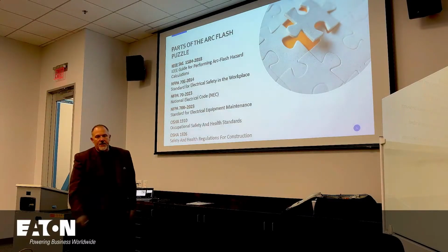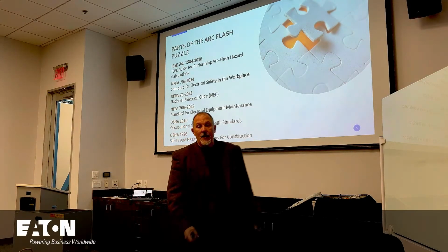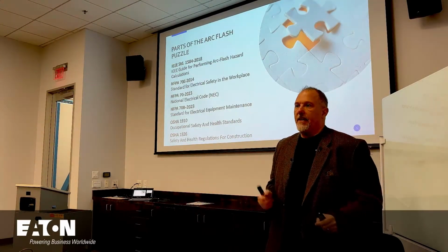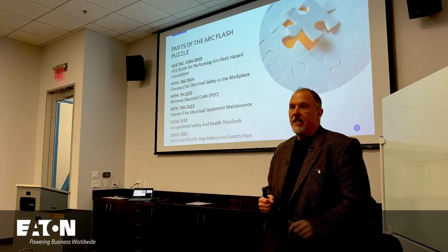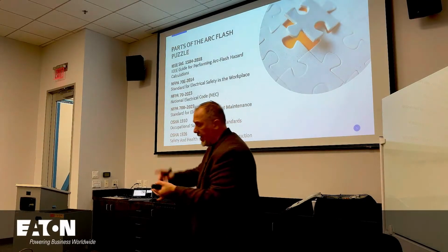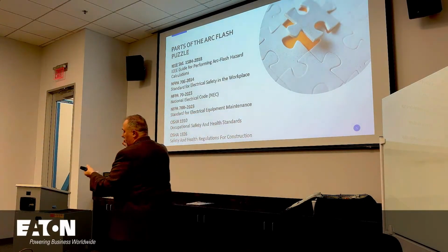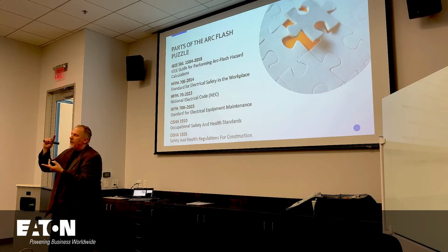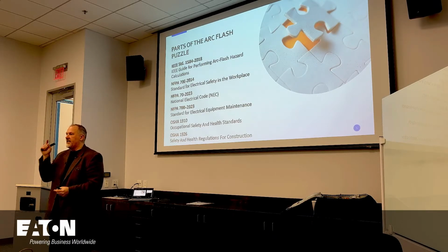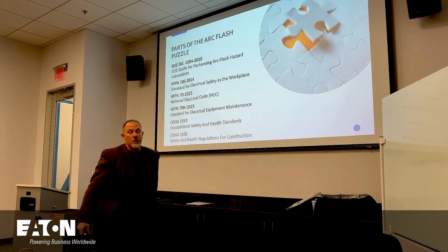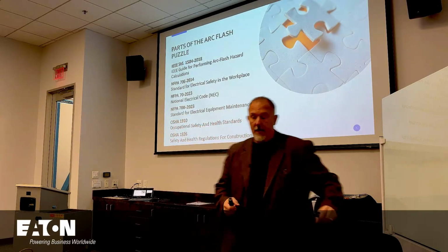OSHA. OSHA is the enforcement arm for 70E, right? Because I don't have an AHJ walking through my facility and inspecting to 70E. They'll inspect to the National Electrical Code, and if the National Electrical Code says you have to have ground fault circuit interrupters, if they tell you you have to have barriers to reduce likelihood of accidentally coming in contact with something, if they tell you you need working space, they can tell you all of the things around the installation, but they're not going to enforce your safety plan. Unfortunately, some of us will experience that through the OSHA investigations after an event,